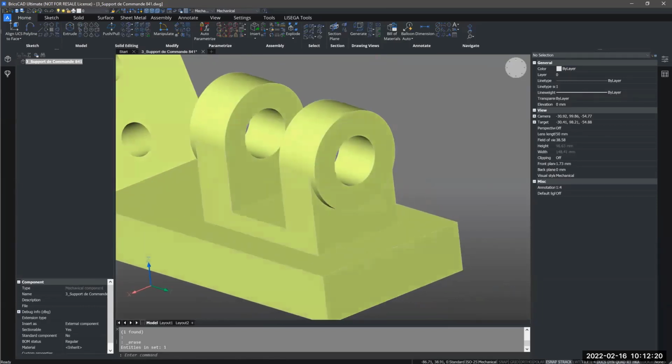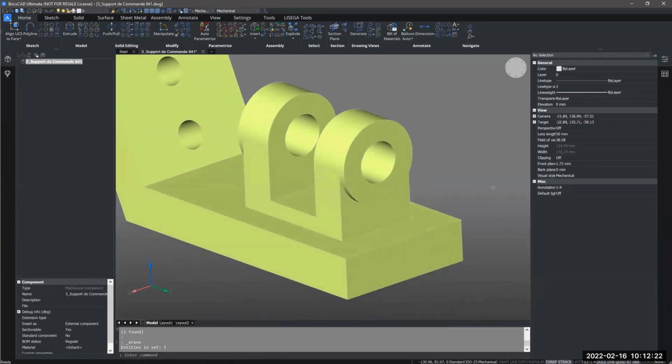So to fix this, we have a command called dm simplify. So I will just type in dm simplify and hit enter. Then I can select what geometry and entities I want to apply it on. I want to do it for the entire model. So I will select the entire model in my command line.